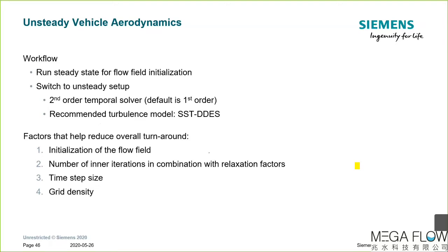We know for unsteady aerodynamics, there are a couple of parameters in order to speed up the simulation. Initialization is an important aspect, as is the number of iterations per time step in combination with a smart choice of relaxation factors. This of course depends on the mesh quality, how hard you can push the solver, the time step size, but also the mesh. So there are a couple of parameters at the end of the day.